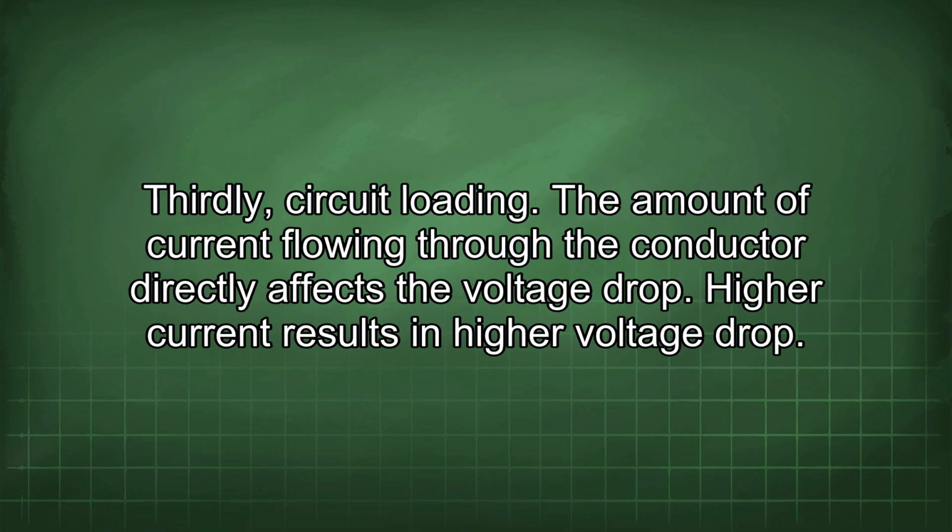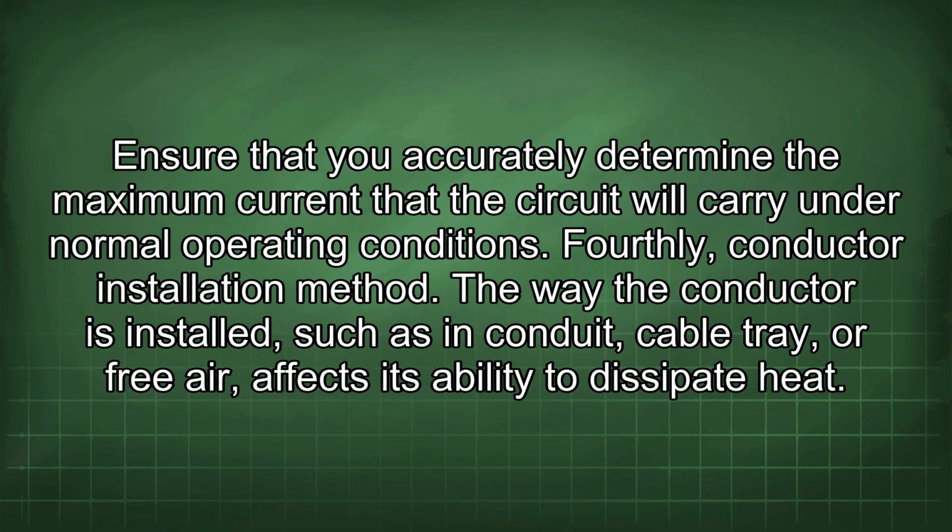Thirdly, circuit loading. The amount of current flowing through the conductor directly affects the voltage drop. Higher current results in higher voltage drop. Ensure that you accurately determine the maximum current that the circuit will carry under normal operating conditions.